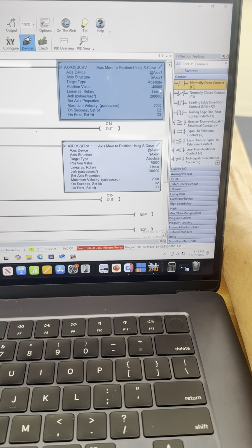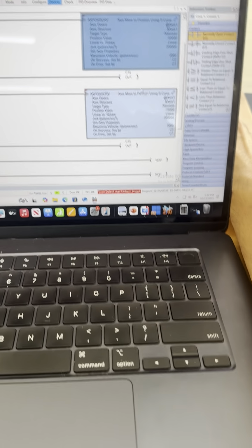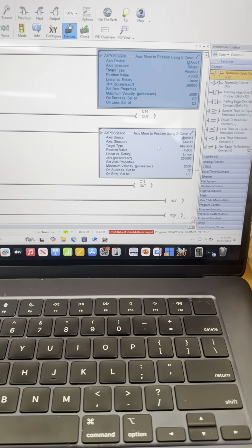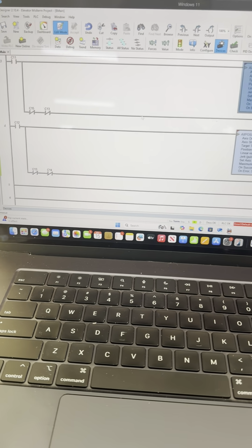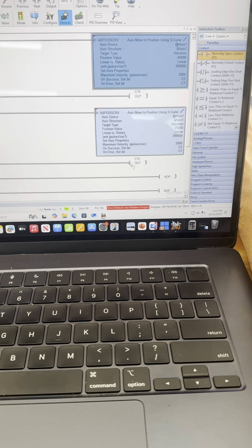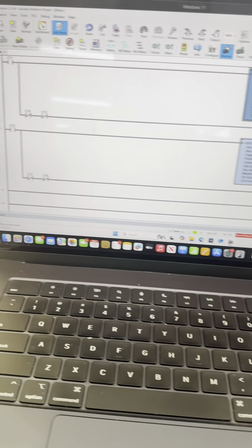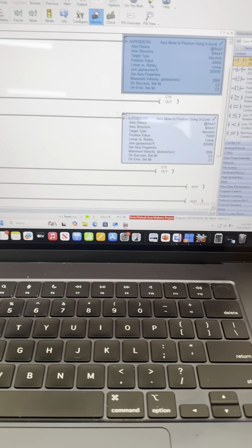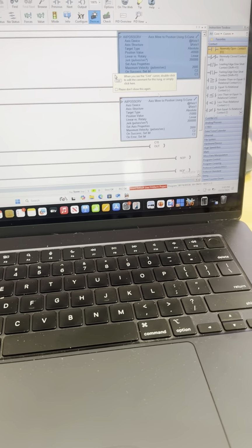The second floor being negative 40,000, the third floor being negative 75,000, and the velocities are the same across all three function blocks. And in parallel, we have the same two other normally closed memory bits for the floor text from the HMI, which allow for only one floor to show.